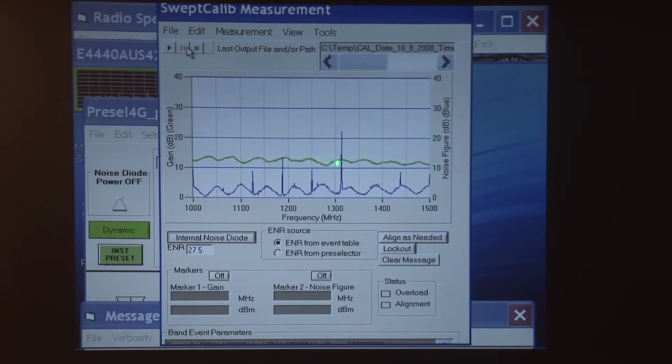is. And this gain is a function of the gain in the low noise amplifier in the RF front end box, the losses between the front end box and the spectrum analyzer, and the noise figure of the spectrum analyzer itself with its own low noise amplifier turned on.